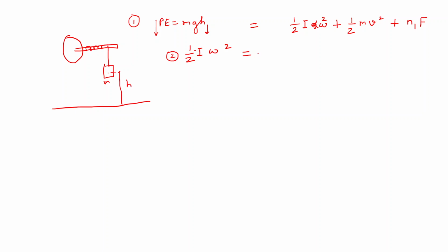And what is the reason? That happens because of friction. Because there is friction between the ball bearings and the axle of this flywheel, it will eventually come to a halt, and that will depend again on the number of turns we are counting after the mass detaches. So that is the number of turns the flywheel takes, and F is again the same frictional constant. So this kinetic energy will be equal to this frictional energy. This motion will come to a halt because of this frictional energy.